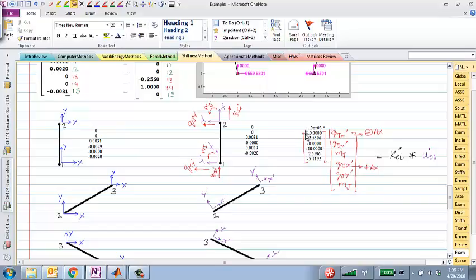That makes sense, right? The first component here, I don't know if you can see that from back in the room, but this is negative 10 times 10 to the power 3. This is negative of 10. This is already negative 10. So the axial force in the first member is what? Compressive or tensile? Since the value is negative, it's compressive.